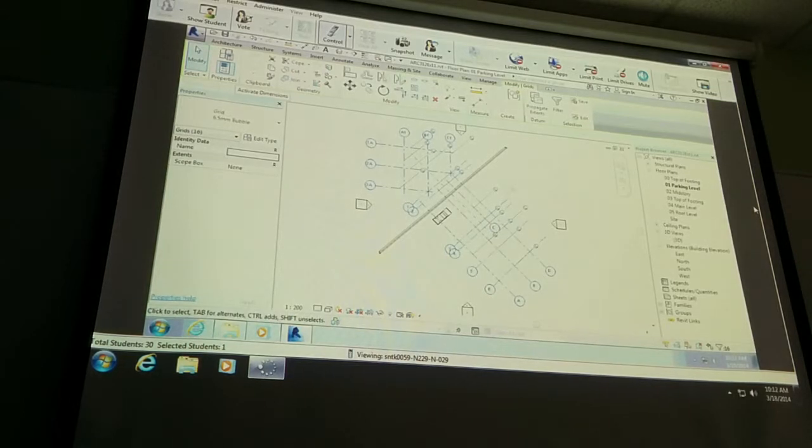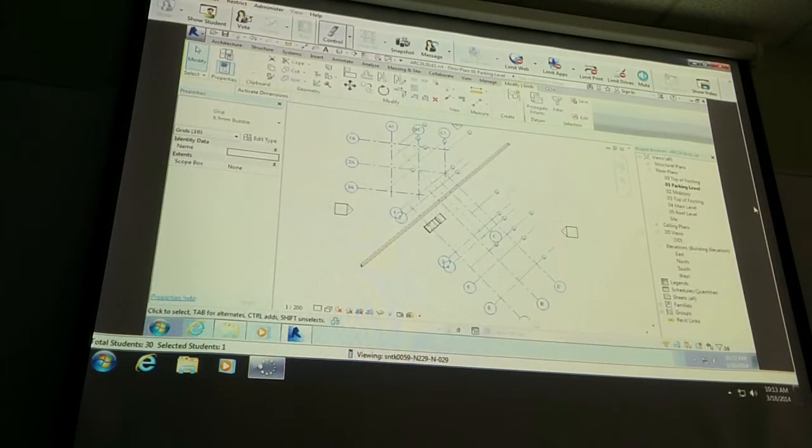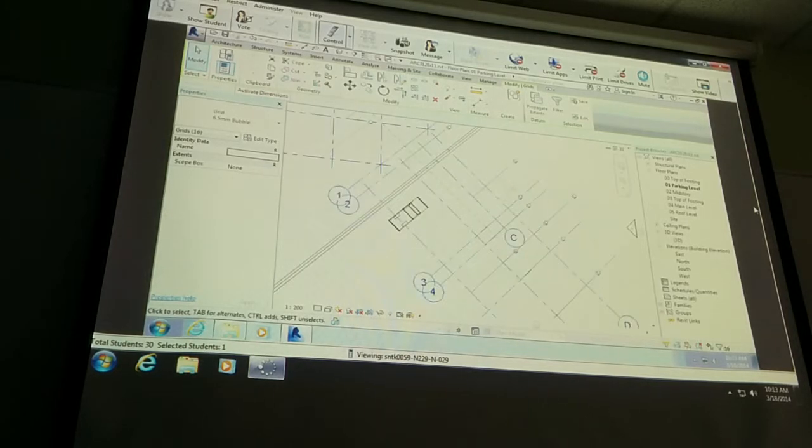Which means, if you want to change one in the future, like let's say you go to a section view or an elevation view and you find out the tops don't line up, in order to make the tops line up, you'd have to unpin first and then you could repin them again. So when you pin something, it kind of freezes it, right? You can't change it until you unpin it first. And it's just to prevent you from moving something or stretching something by accident.